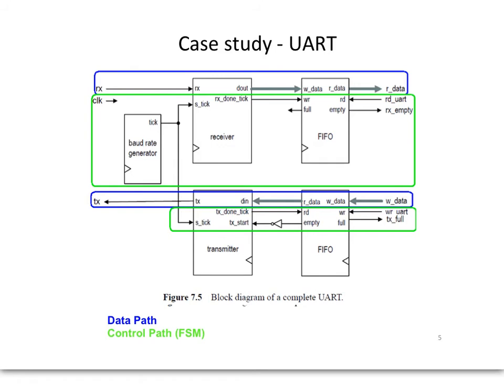The opposite direction is when we want to write data, then we would have a byte that we can put into the FIFO, if we have the FIFO enabled. The FIFO can then put a byte of data into the Uart transmitter, and the Uart transmitter can send data bytes bit by bit onto the serial line. So this is the data path of the Uart, or the two data paths,